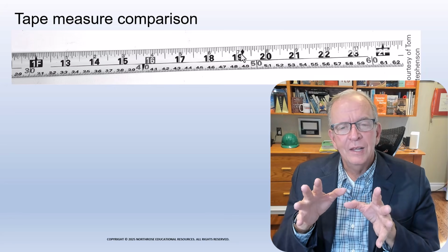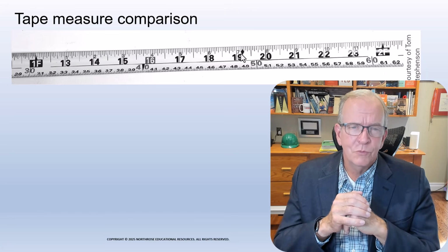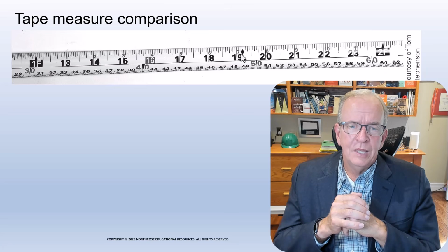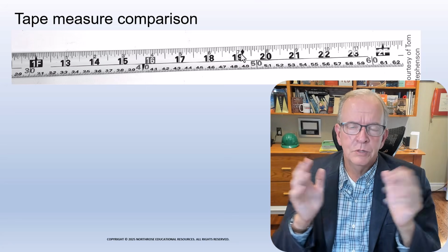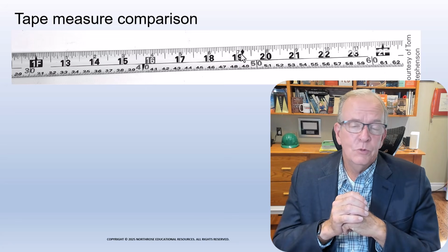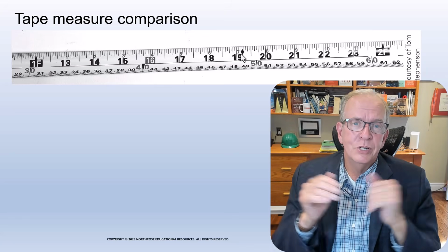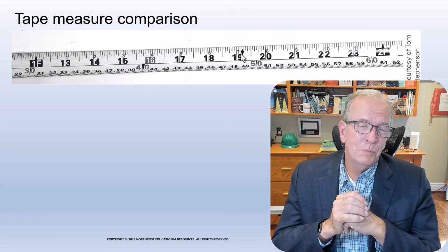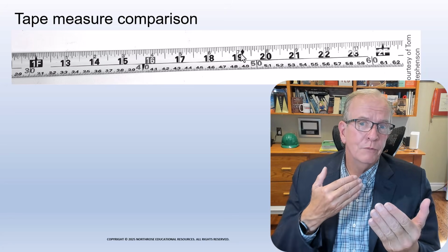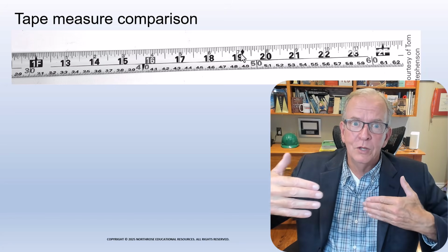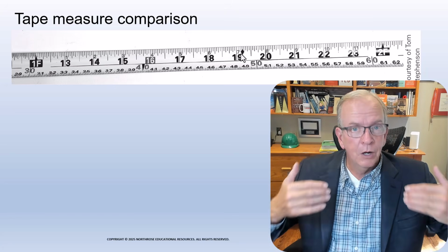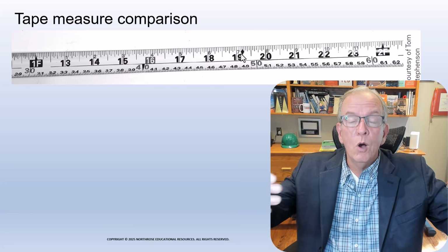But beyond that, it was very interesting. That wasn't really the core reason they were doing it. The core reason was, well, they were upping their game at the time for Energy Star home certification. And it's a more energy efficient house. You've got less thermal bridging through the studs. And they were building with 2x6s, not 2x4s. We, for years, built with 2x4s, but we went to 2x6s so we could fit more insulation and meet new building code standards for high R values. R value is resistance to heat loss through the wall.